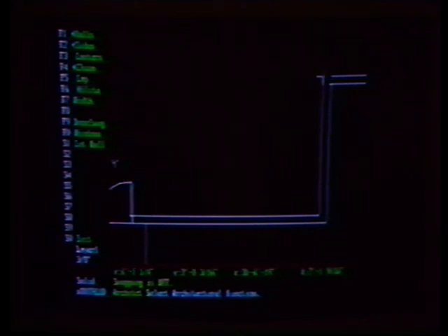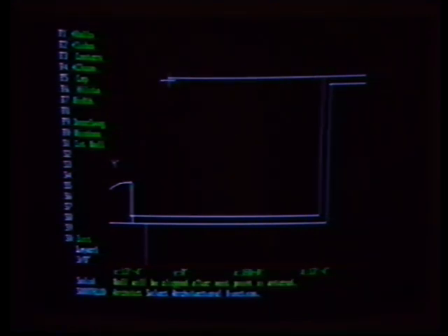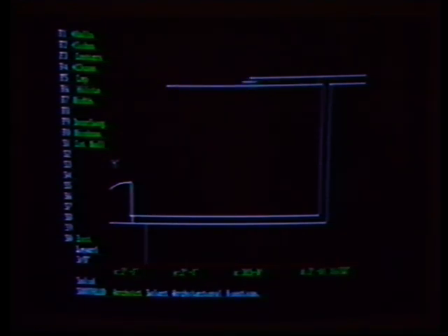First, I'll turn on the walls. I'll come out to the point where I want to start the wall, and we'll extend the first wall to the left, locating the other side of the wall as we go, and notice that DataCAD clips out the new wall to the existing location. Then I can come down to where the wall is going to stop, locate the other side, and DataCAD will automatically clean out the wall.